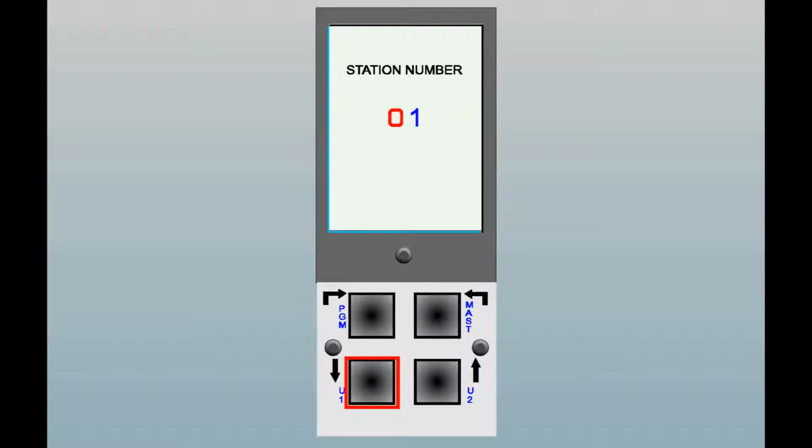Also, now you can set up a 2-digit station number if desired. And this 2-digit number will be displayed on the front lower part of the LCD panel, and it can also be included in the data transmission if desired each time you press a reading. You can also set up a 2-digit column number if you desire, and it is also displayed similar to the station number. And it is also transmitted in the data transmission if you wish.